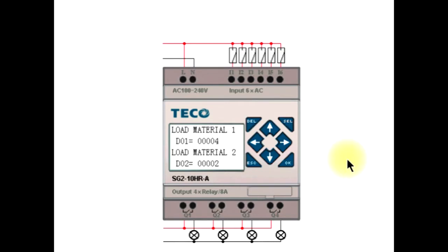You can see it immediately changed to load material 1 and load material 2. That is to make it extremely easy to navigate through the system. That is the operational screen that you use most of the time during normal operation to change the load time for either material 1 or, if you have a 2 material loader, material 2 or the regrind. This screen will display for 2 minutes. Then it will go back to the main screen.